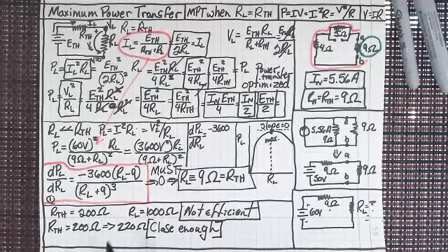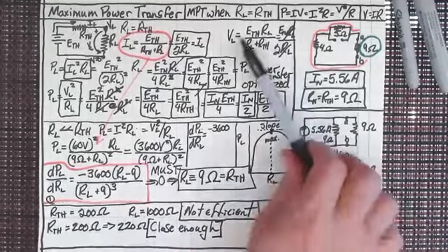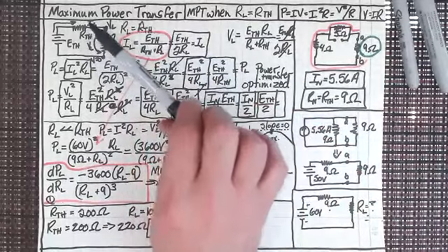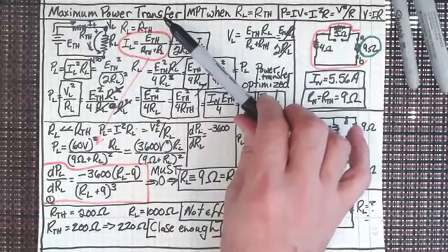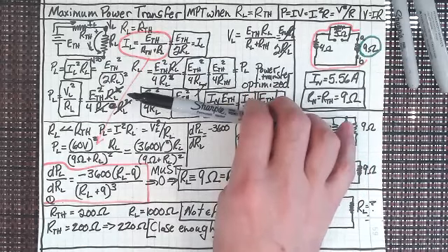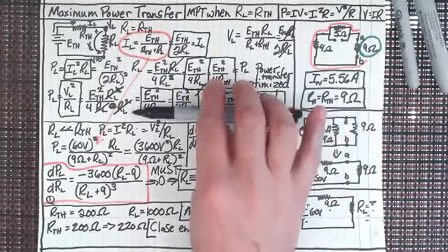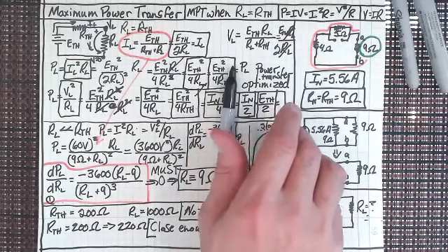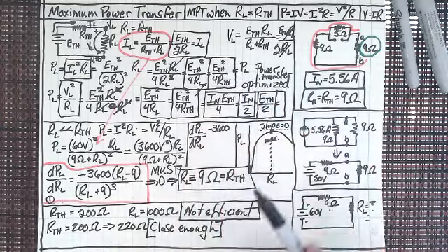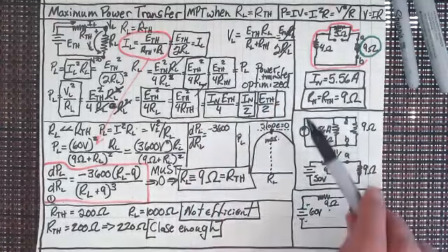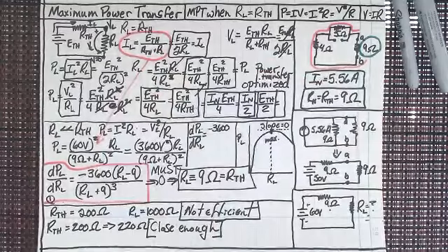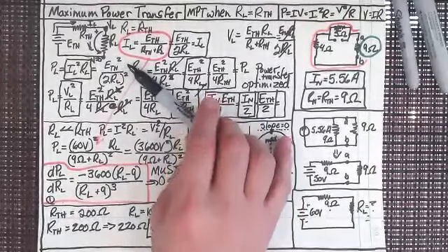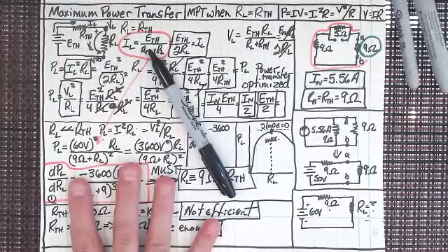That's the thing I want you to take away from this lecture, is that with maximum power transfer, when you're trying to transfer something through there, you want to make sure that whatever the resistance is in the circuit, or whatever type of voltage source you have, and the internal resistance of that, is going to match up with the type of load that you're going to put on that circuit. Does everyone understand that? Why we use this maximum power transfer, and that's why I derived all this.